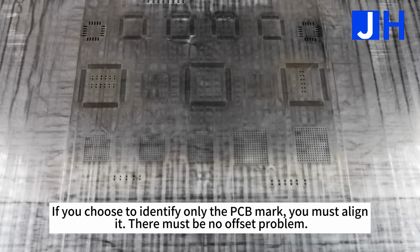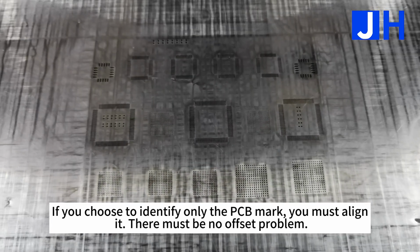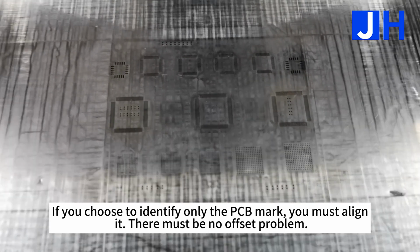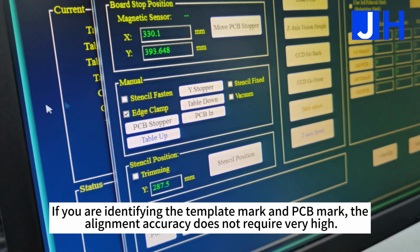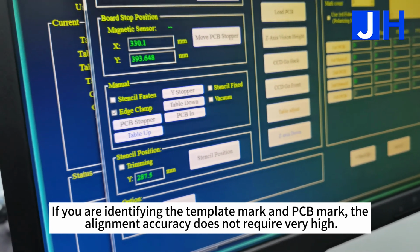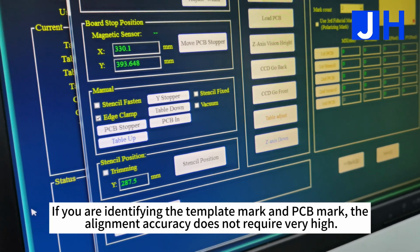If you choose to identify only the PCB mark, you must align it. There must be no offset problem. If you are identifying the template mark and PCB mark, the alignment accuracy does not need to be very high.